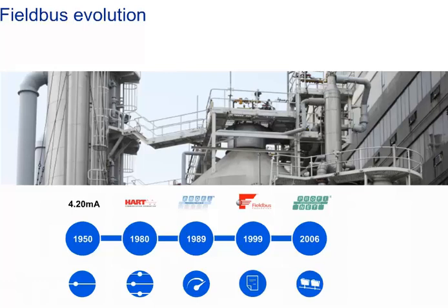For the time being, this technology is solely used in the production industry and not in the process industry. That is why Profinet will not be considered in these modules. In 2008, the latest bus technology innovation was launched, wireless HART. Here, the well-known HART protocol is transmitted wireless by a field device.